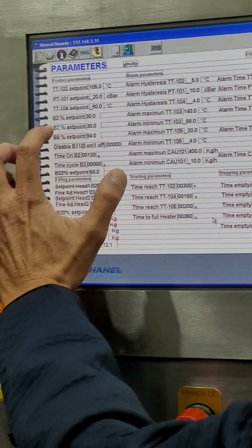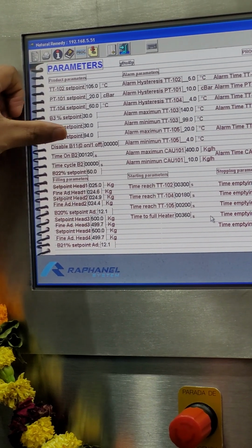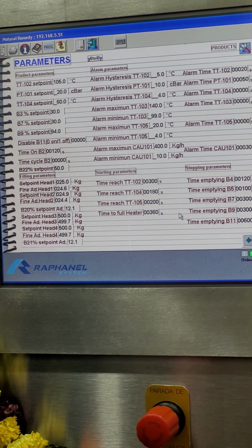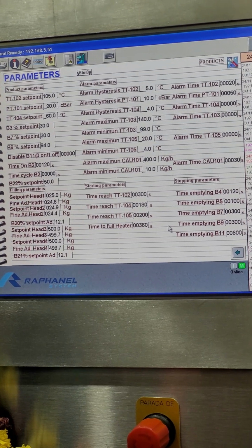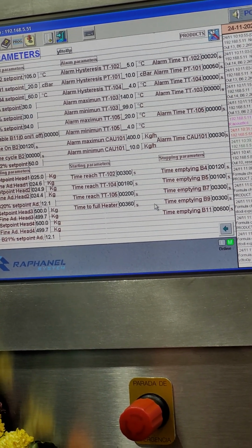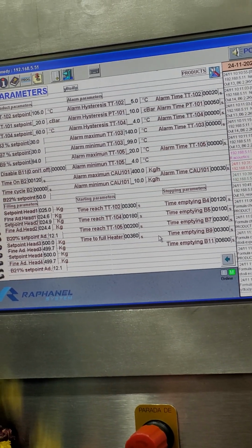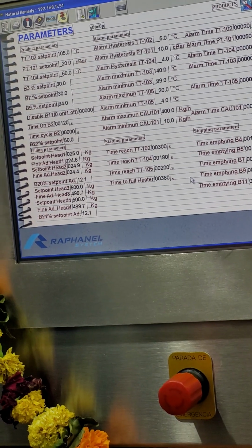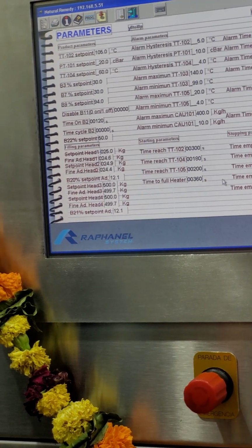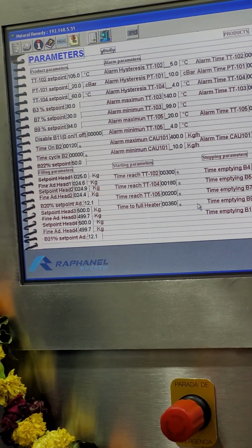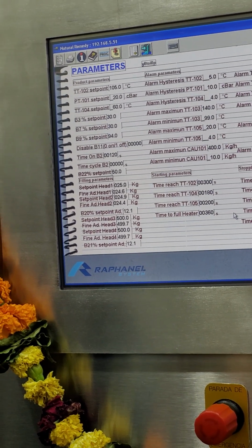What is the optimized setting for set point here? You're showing now 94. 94 is standard. Less is better. Optimize, for example, for a powder, perhaps 90 is enough. For example, whole ginger or whole seeds: if you see big pieces that don't move, because you see that the material is accumulating, then you have to increase the speed a bit.